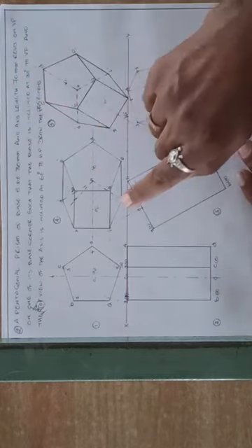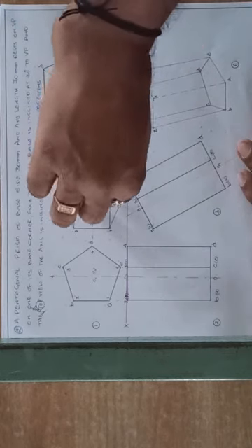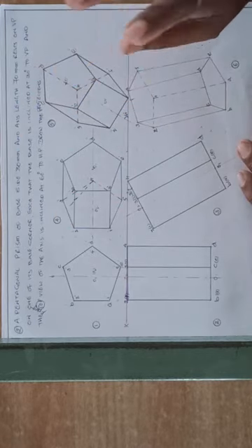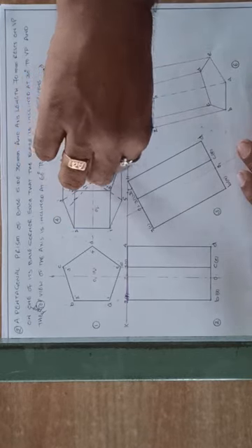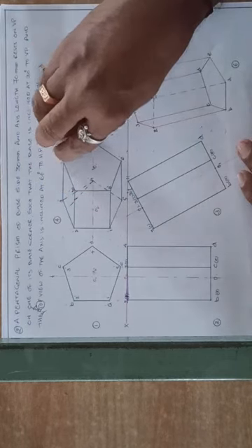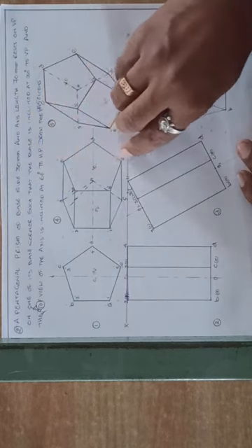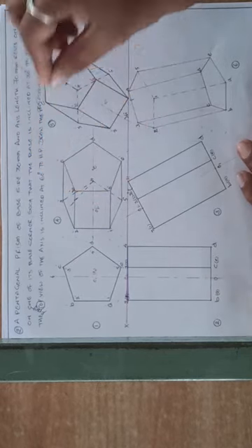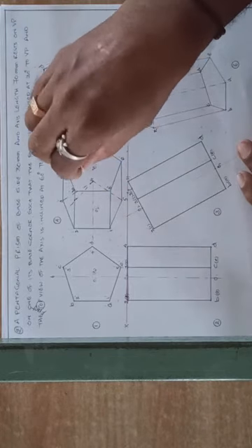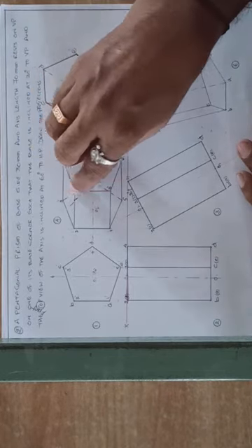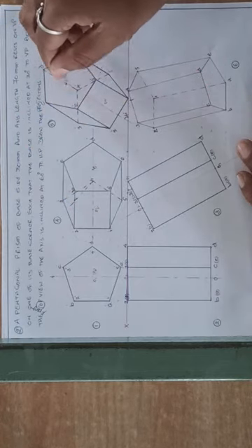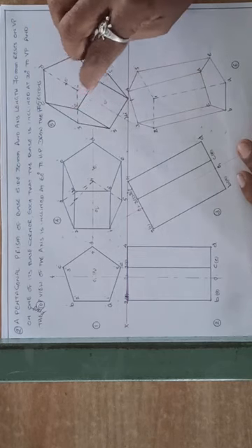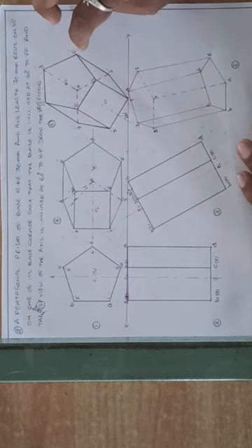Right. Similarly, now take another center, that is O2 to O1. Here O2 to O1, mark the distance here. Same procedure from this center line, axis line to D. Then there is a vertical line which is connecting C dash and E dash. From O1 to that line, transfer the same distance here. Again from here to this A dash B dash, that distance also, just from the center transfer here. Now you are getting the points A dash, B dash, C dash, D dash and E dash.